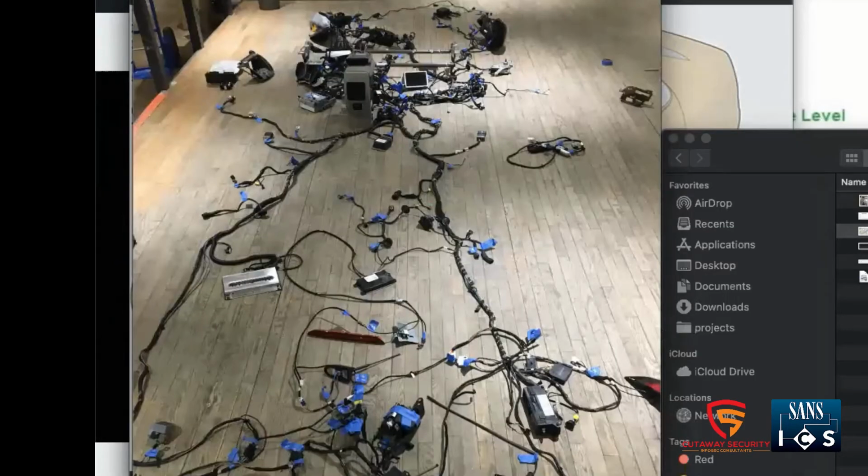So if OEMs can add whatever devices they want on here, assuming that it conforms to the top level design that they had for the car, how do the different devices know which ECUs are sending out messages and which ones they should listen to? Let's talk about the second part first. Each device is programmed to know what messages it's interested in. For example, the engine knows that it needs to listen to the transmission, and maybe some heat sensors. So while it might be electrically receiving all of the messages on the bus, there's some kind of filtering going on where the microcontroller decides what it's actually interested in acting on.